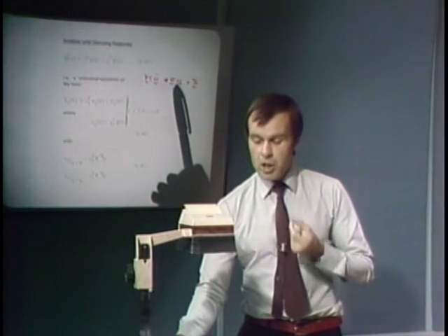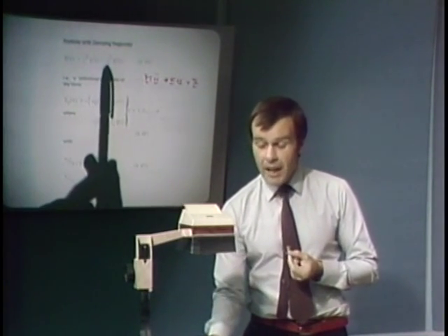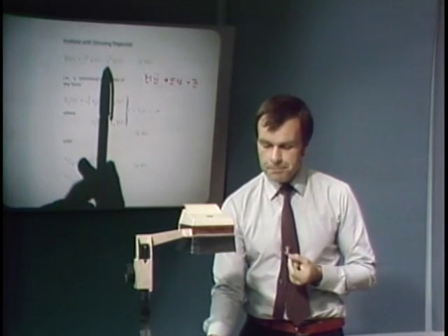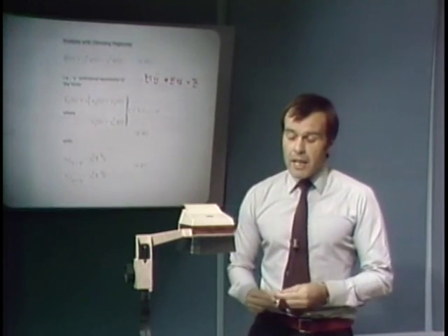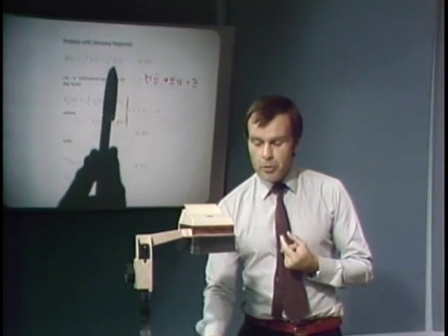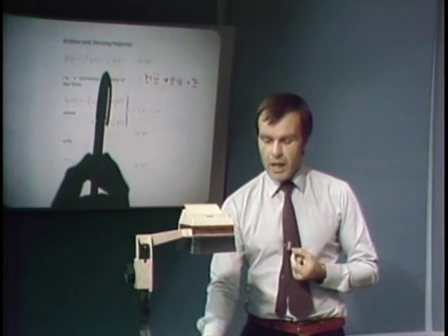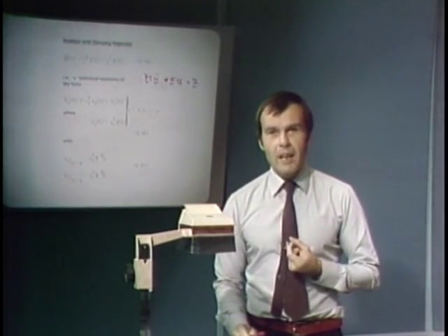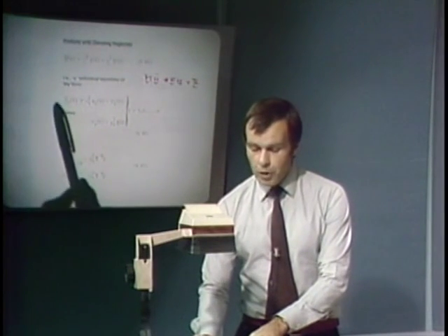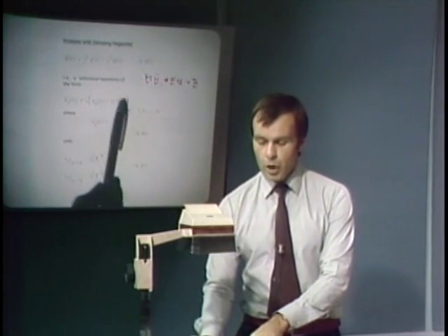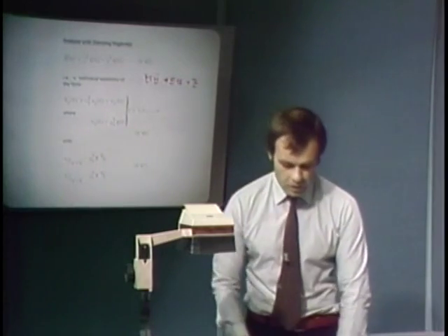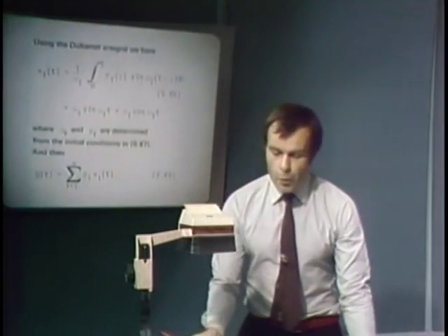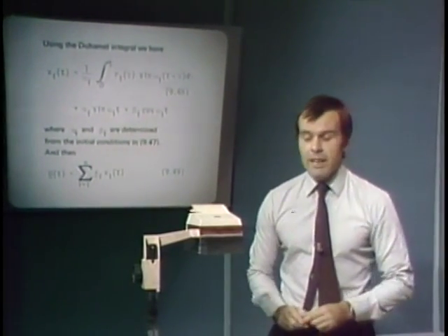And this transformation is effective if we can find the phi matrix that we're using in the transformation very cheaply, very economically. Well, the effectiveness of mode superposition goes beyond what I have just described. The important point in mode superposition analysis is that we do not need to solve all of these equations, that we do not need to solve and look at all of the decoupled equations. But let us first look at how we can solve the decoupled equations exactly.